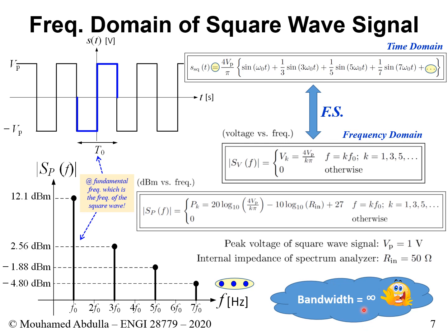bandwidth. So this is where you apply a trade-off, and you say, well, I'm gonna stop at some level of harmonics, maybe the 5th, maybe the 7th, maybe the 9th, maybe the 11th, maybe the 13th, and I'm okay with the approximation. And also the bandwidth will be finite. So you won't get a perfect matching signal, but you'll get a finite bandwidth.